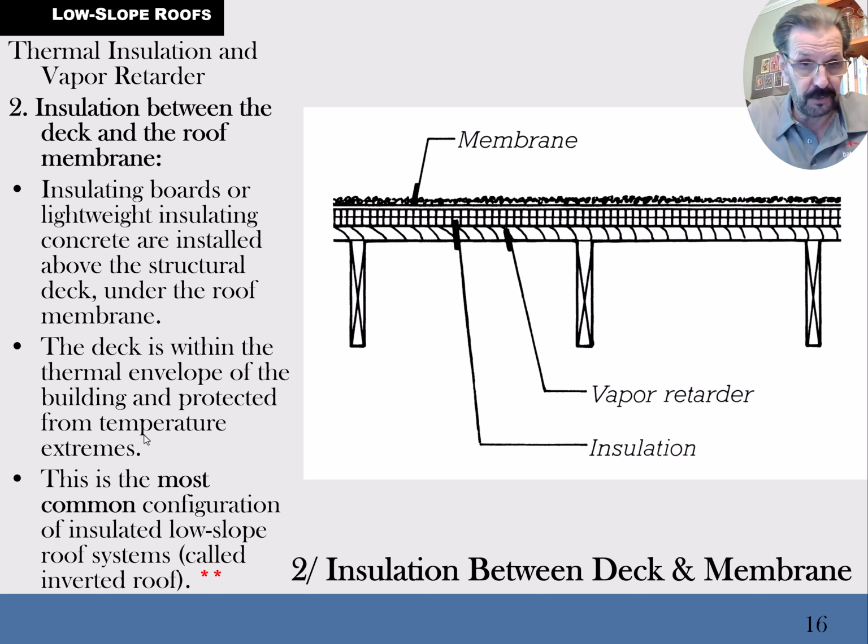It's called an inverted roof, and this is more common than anything else as far as modern roof decks on the commercial buildings. You see it a lot. And then there's a little squiggly stuff they're showing up top. Well, they got the membrane down there, but then they put the gravel. They still put gravel down on top of all of that to protect the roofing material because it's exposed otherwise. Okay, so that's case number 2.